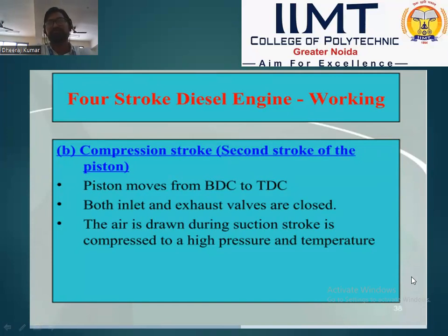During the compression stroke, the piston starts at bottom dead center and moves from BDC to TDC. During this stroke, both the inlet and exhaust valves are closed. Air is compressed during this stroke and the air temperature increases. At the end of the compression stroke, the fuel injector injects the fuel inside the cylinder.